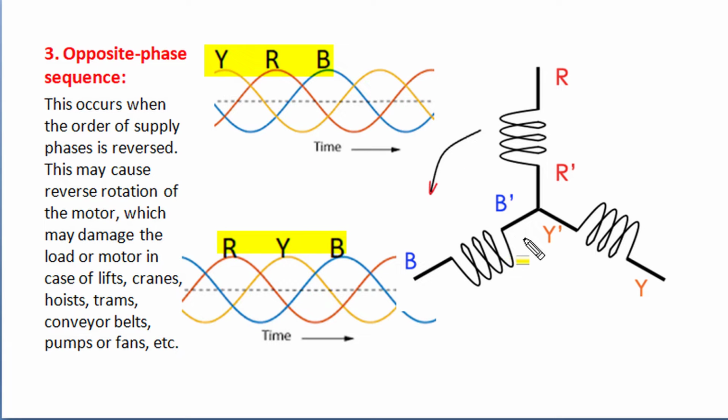Now in a three-phase induction motor, the stator windings of three phases produce their magnetic fields at three different electrical 120 degree displaced axes, and when we supply three-phase time displaced excitation to the three-phase space displaced winding, it produces a rotating magnetic field of constant magnitude and constant synchronous speed, and the direction of rotation of the magnetic field is from the magnetic phase axis of the leading phase to the magnetic field axis of the lagging phase.